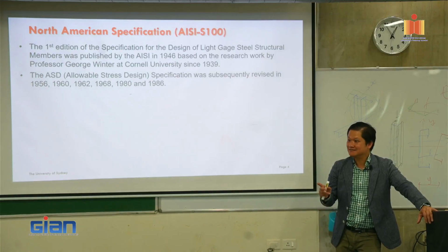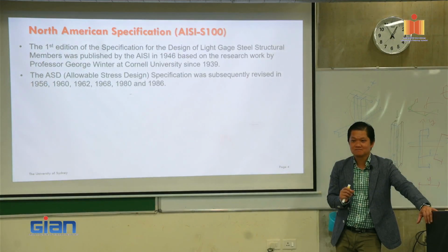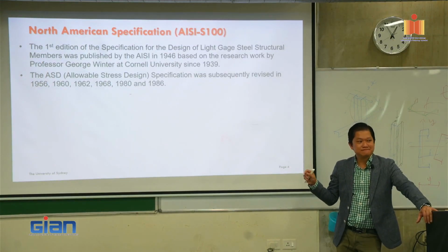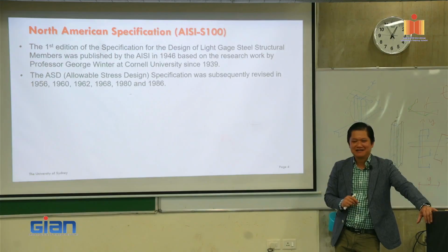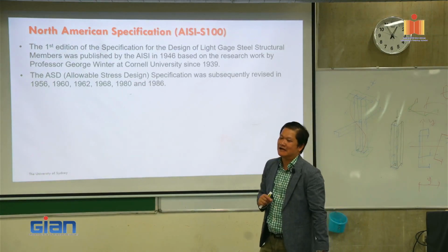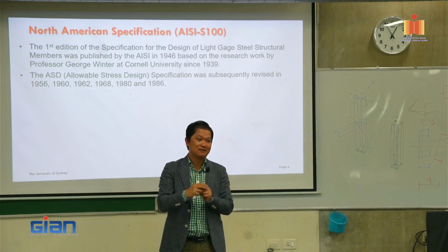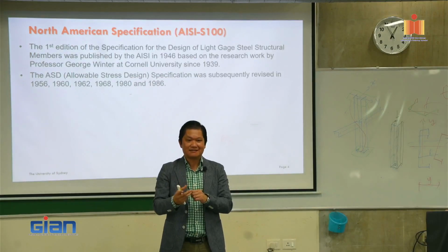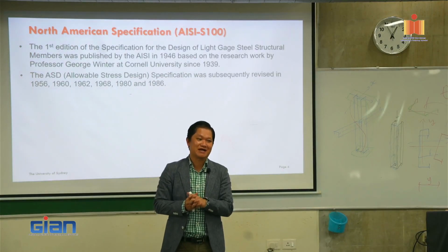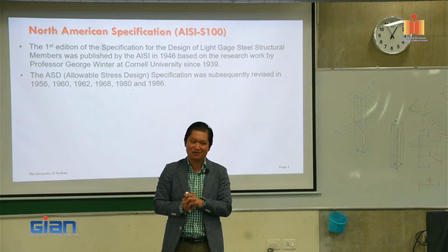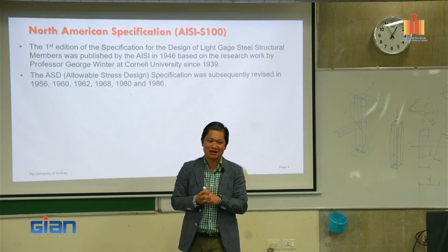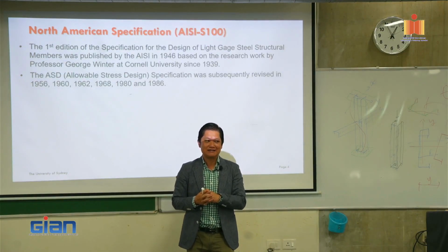Thank you. Any question? And just on this one, when you design a Z section, it's more complicated as well. At the moment, for the Australian standard, we assume that the Z section is a C section. We just treat it as equivalent and design for that. But the Z section, as you saw, is a point-symmetric section, and calculating the buckling load is a lot more complicated. We don't have a model now to calculate it accurately. So that is the first one.